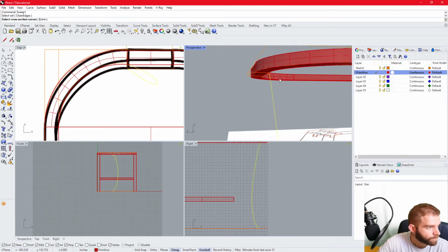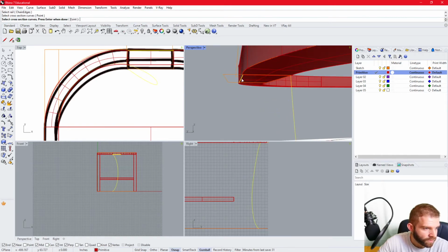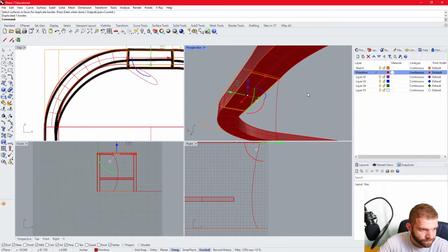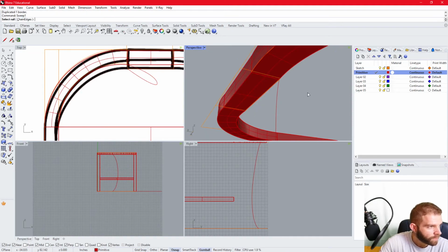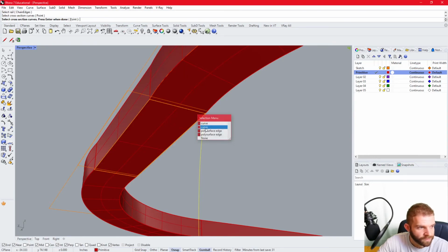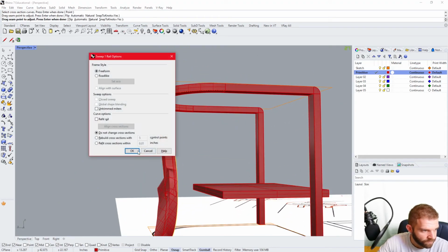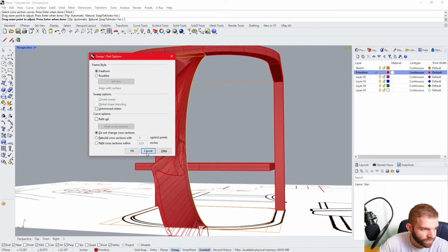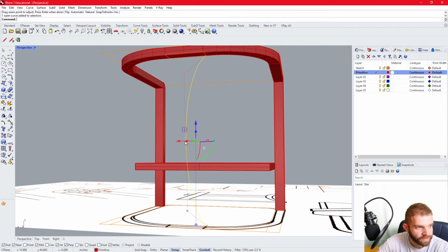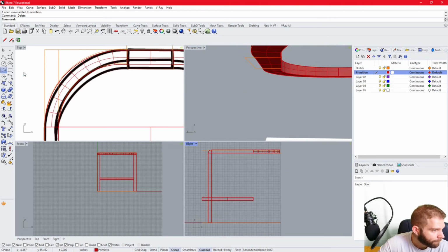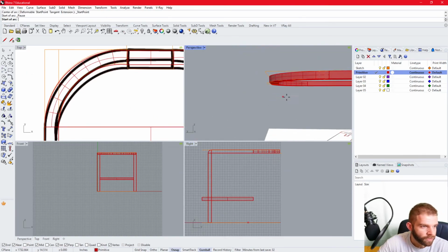Here's our rail. And here's our cross section. I actually need to duplicate the face of this top piece in order to do my sweep. Select my rail, select my cross section. Seems okay. Now I have something funky happening down here. My curve isn't quite made correctly. Let's just go ahead and delete it. I showed you how to change those points, but I'm going to go ahead and delete. So once again, I'm going to set up my arc in perspective view.